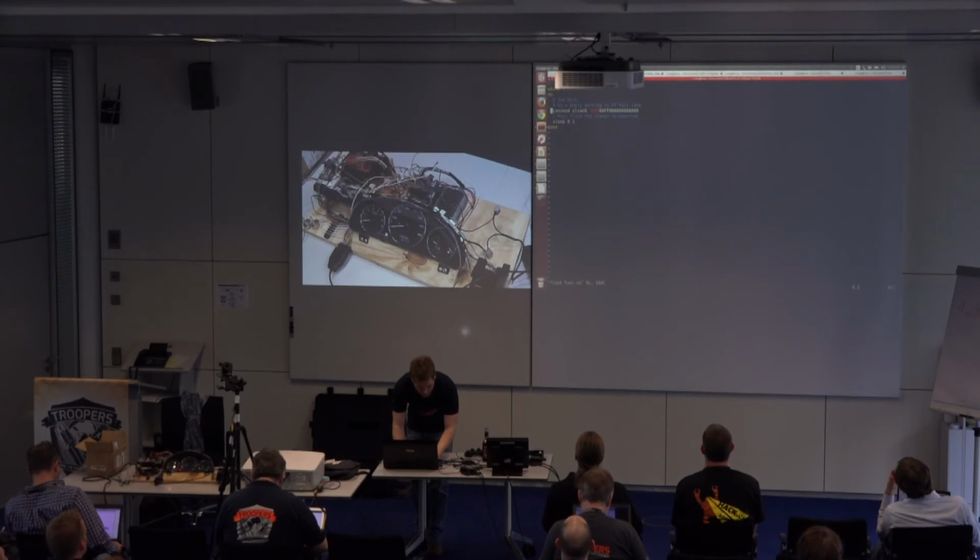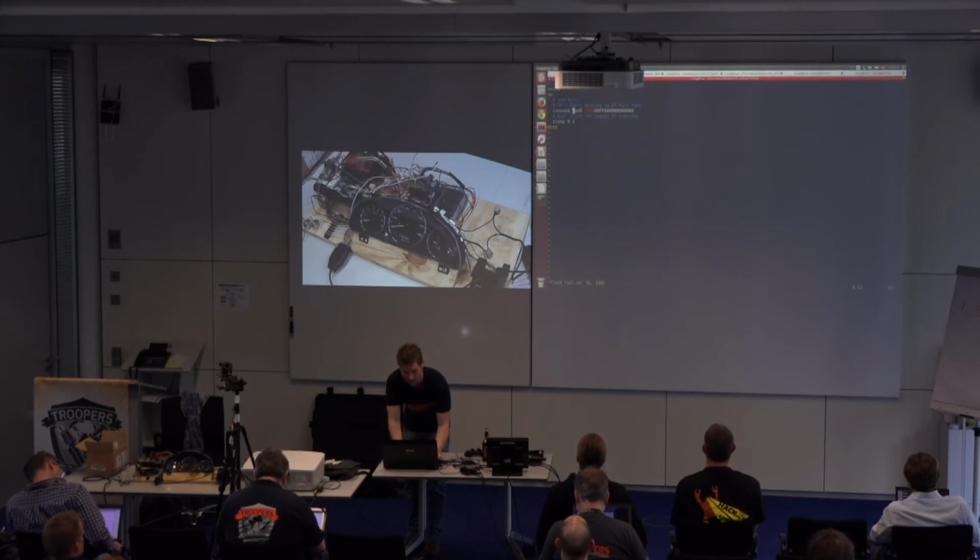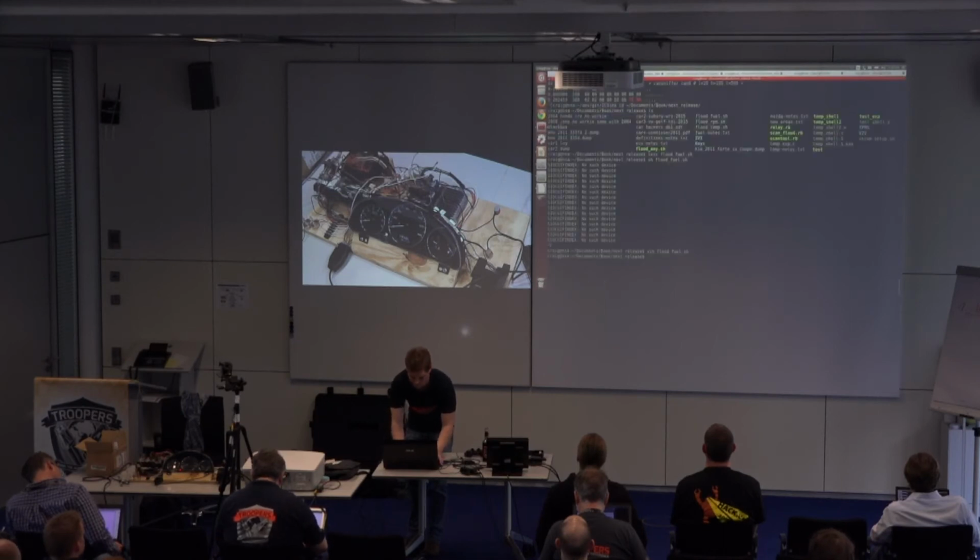What are we talking about? Oh yeah, so that was a serial line CAN. Those are the three things you pretty much see in SocketCAN. You see either CAN, SLCAN, which is serial line, and then VCAN, which is virtual CAN. If you're using a physical device, you have either SLCAN or CAN. SL just means it's usually a cheaper device that does serial. Like I said, I didn't really have a problem using SLCAN.